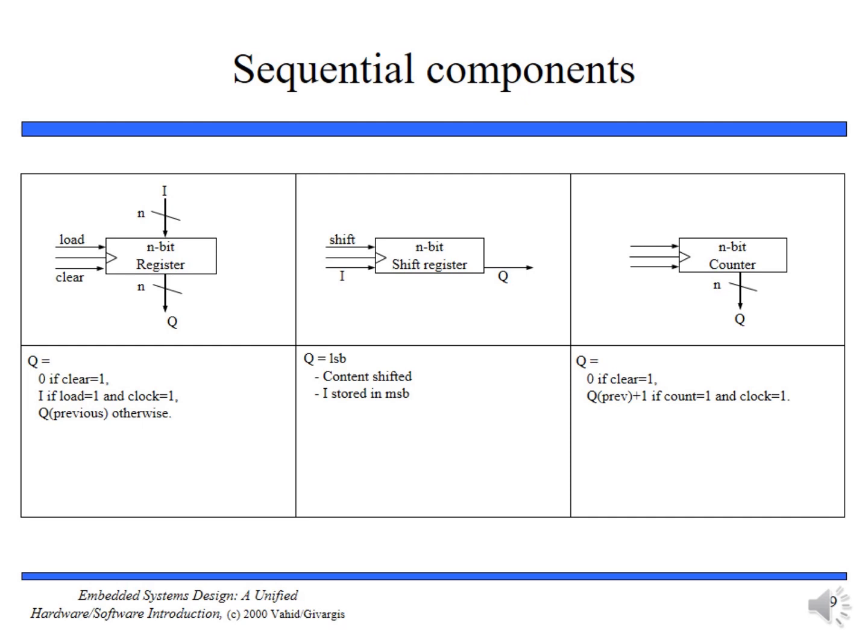One of the most basic sequential circuits is a flip-flop. Okay, so all these, this one, this one, this one, you can see there is a clock with an arrow. Okay, so all these possess flip-flops because they are going to depend upon their previous inputs. A flip-flop stores a single bit. The simplest type is the D flip-flop. Now listen carefully. It has two inputs, D and clock.